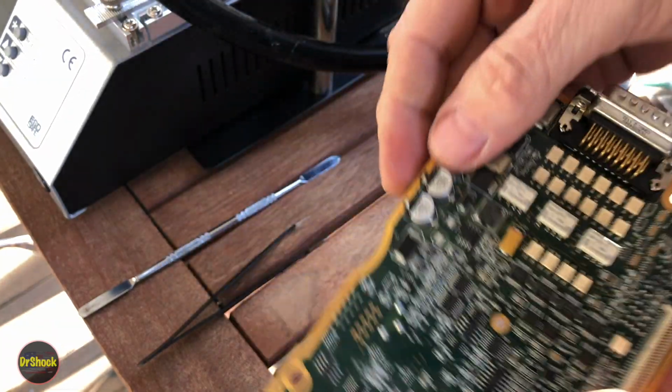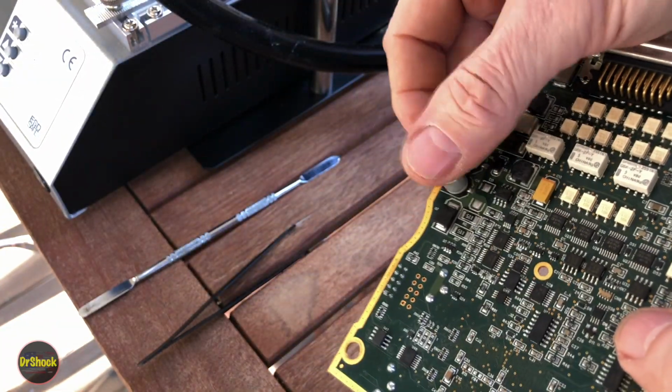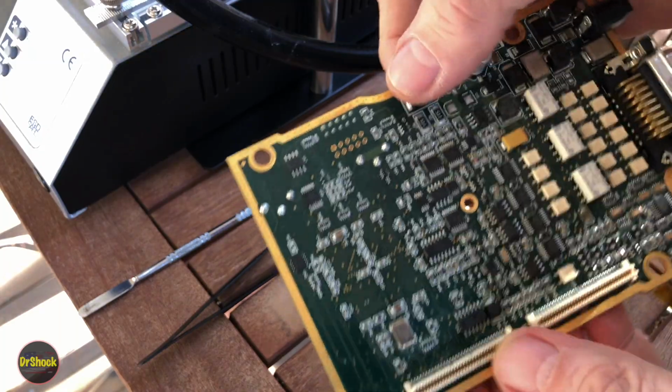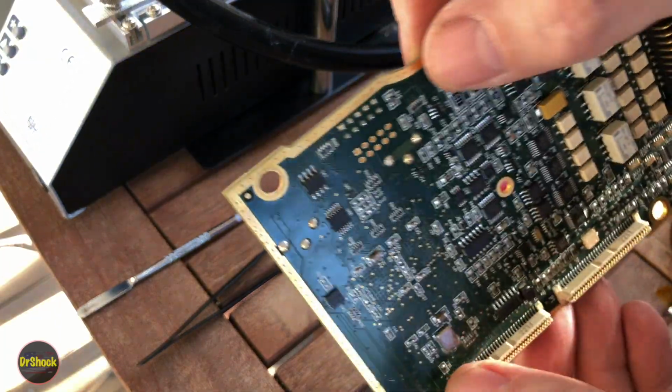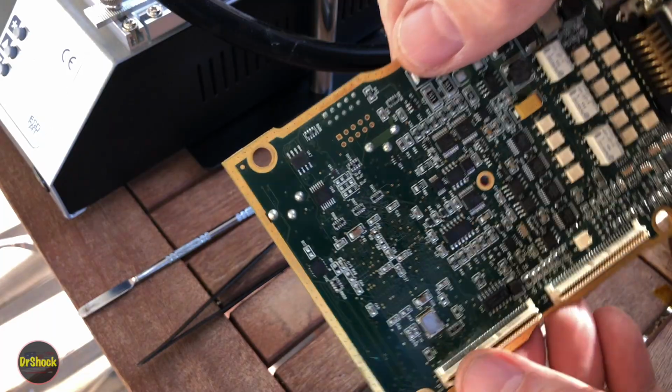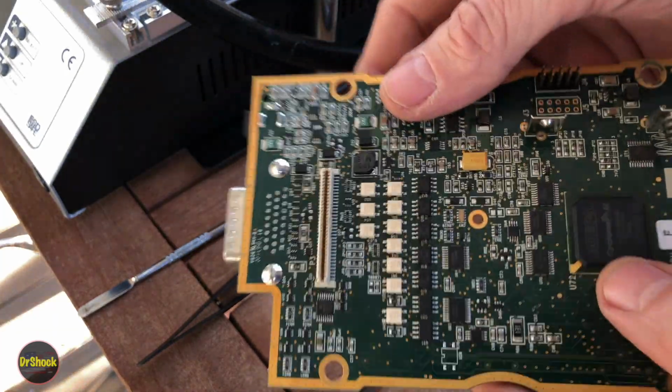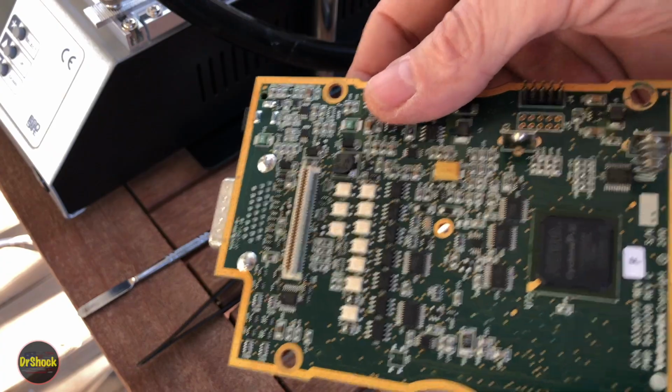We've got a couple of electrolytic capacitors over here that we want to make sure we don't overheat and have them pop on us. And we're probably going to want to Kapton off this set of plastic connectors here just so they don't get damaged as well. But other than that, it should be just like the one we just did. We'll give that a shot and see what we get out of this guy.